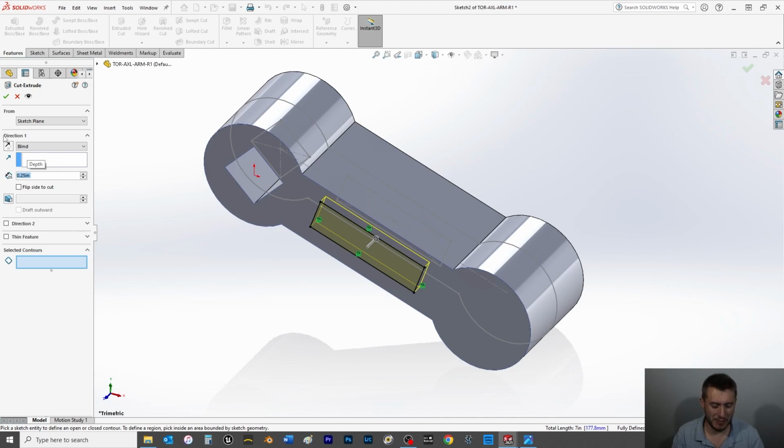This is going to be some sort of probably cast iron, maybe cast steel, or might be forged steel. But even if it's forged, I believe you'd want to have a draft. So I'm going to go 1/2 inch, .375. And then in the properties of this, instead of adding a draft as its own feature, there's 2 ways to do this. We can add a draft right here. And I'd say at least a 3-degree draft. Probably for what this is.